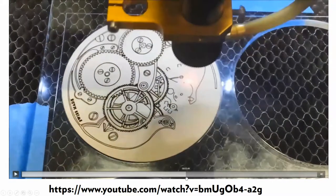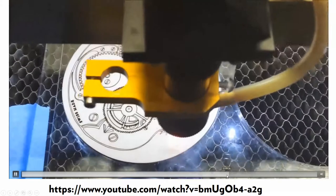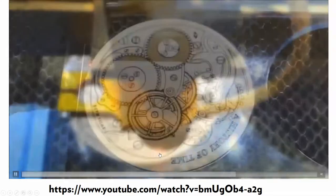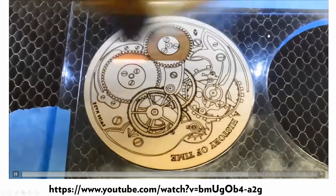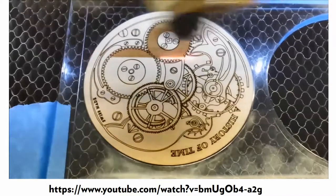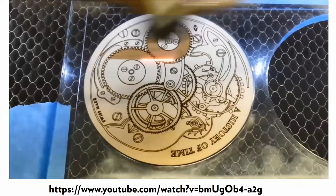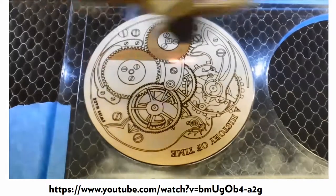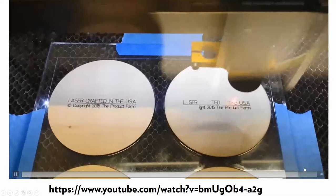I'm going to jump forward a bit here, and shortly they're going to start rastering, and you'll see how quickly these vectors happen, and then here it's rastering, going back and forth, left to right, to color or darken or burn the surface of the interior of those gears to give it a little bit more contrast. So you can see the difference in the speed between vectoring and rastering. And then they put their maker's mark on the back. Really fun.